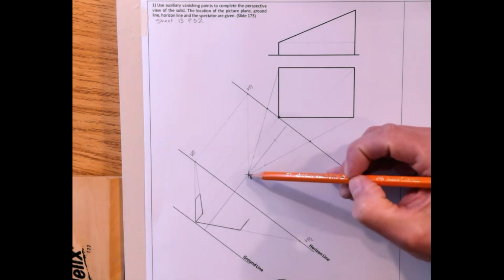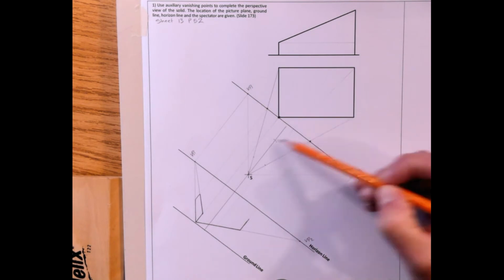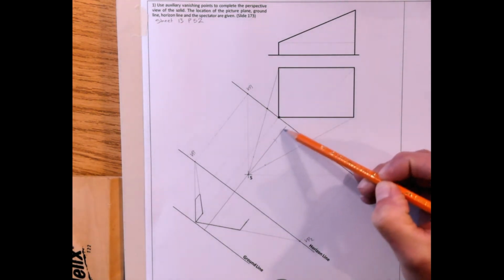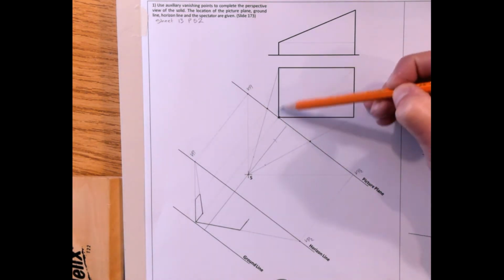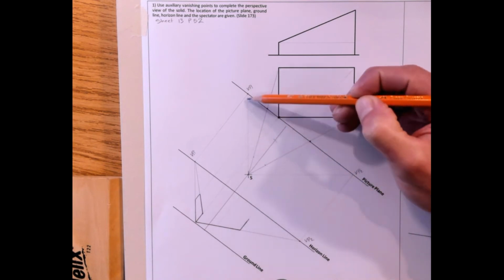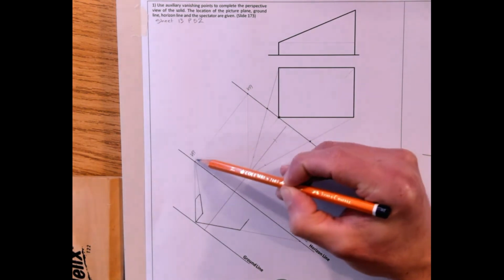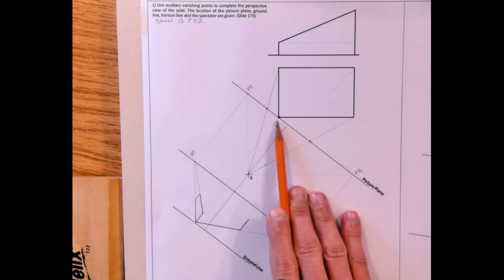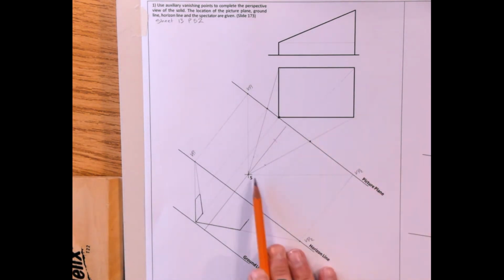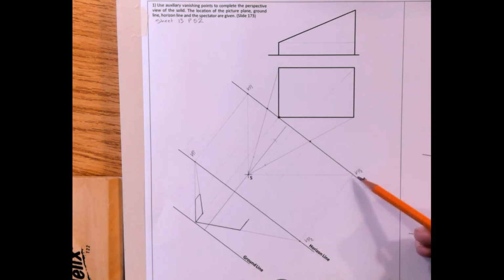So in other words, as we normally would, join our spectator to the widest points on the object, bisect the angle to get our central vision line. To find our vanishing points, we have horizontal lines going in this direction. We go parallel to that horizontal edge, so we get vanishing point 1. Bring it down parallel to the CVL line to get vanishing point 1 in our perspective view. Likewise, there are horizontal lines going in this direction, so we draw our line parallel to get vanishing point 2. Bring it down to our perspective view on the horizon line.